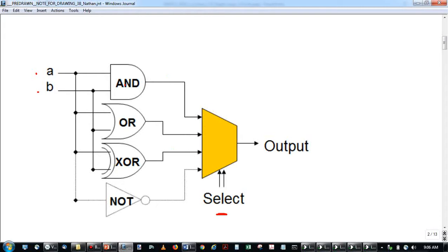You notice there are two selection lines down the bottom here. I mentioned yesterday as well that with two lines I can have these cases: 0,0, 0,1, 1,0, and 1,1. They're the possible cases for two lines. Lines can be on or off, so they represent bits, actually. There are 2 bits down the bottom here. So if we label this one 0,0, this one 0,1, this one 1,0, and this one 1,1, then if I give you 1,0 on the input lines, like this 1,0 here, which one am I choosing? XOR.